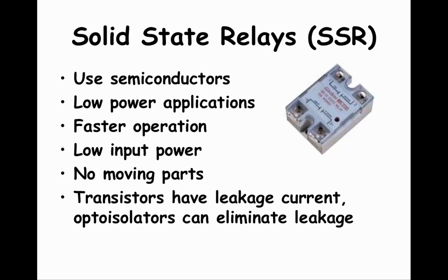It is common that solid-state relays cannot have more than 15 amperes on the load side. So, a solid-state relay that can handle 240 volts and up to 15 amperes can control 3.6 kilowatts of power, which is around 4.8 horsepower.